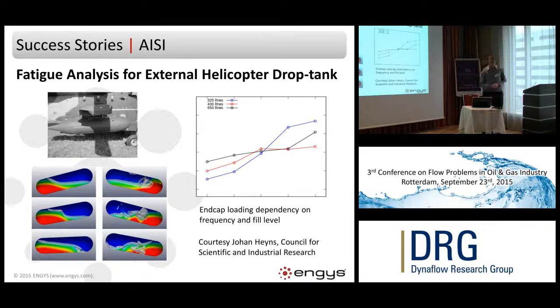This was used, first of all, for fatigue analysis in an external helicopter drop tank. These tanks are expendable, so the idea is to get them to last just as long as they need to last, but no longer. And using the code for this fatigue analysis, one generates some quite interesting, very nonlinear relations between the fill level of the tank, the frequency of excitation, and the loading on the end caps.